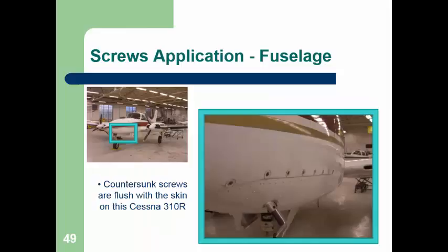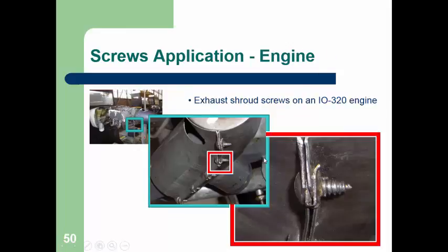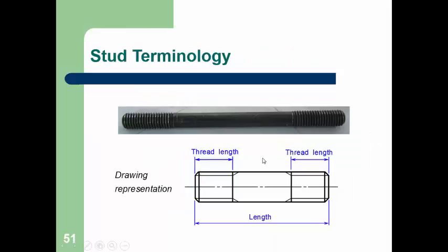This is screw application in the fuselage of a Cessna 310, so that the screw heads are countersunk so that they're flush and you don't disrupt the airflow across the fuselage. Studs.